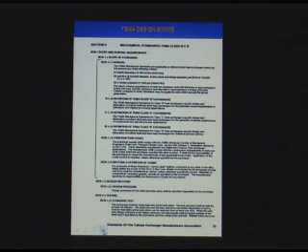TEMA-B would probably be more applicable to a pharmaceutical type unit. TEMA-C is more applicable to a utility type exchanger. But for all of our process work, we apply TEMA-R, which basically imposes a 1/8 inch corrosion allowance on all of the corrodable areas that are identified by the material applications or the material sheet.